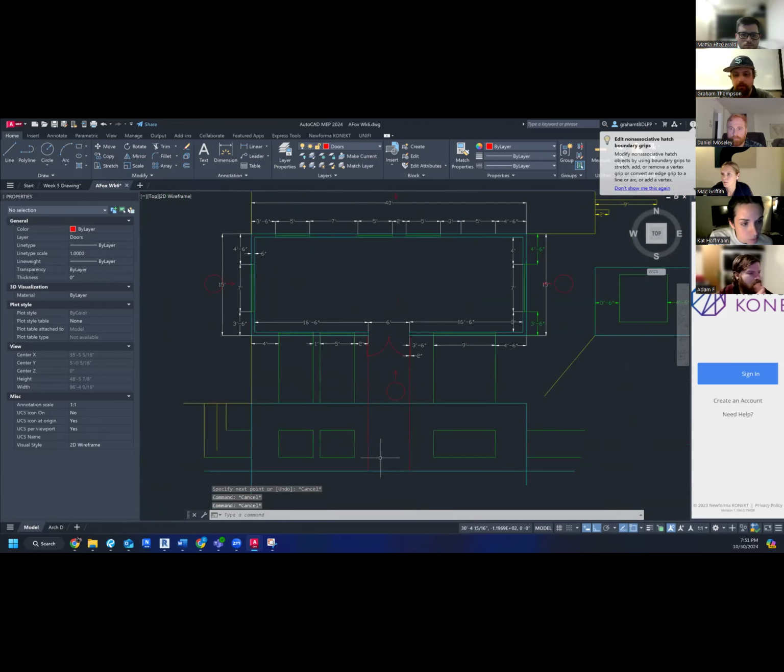All right. Last but not least, let's go ahead and draw a line where the top of our door is. And just to make it nice and easy, let's trim it up. Trim out all these other pieces of that door. And then now that I've got all those pieces trimmed out, I can grab the center point of this line. And now I've got a kind of a door, right?